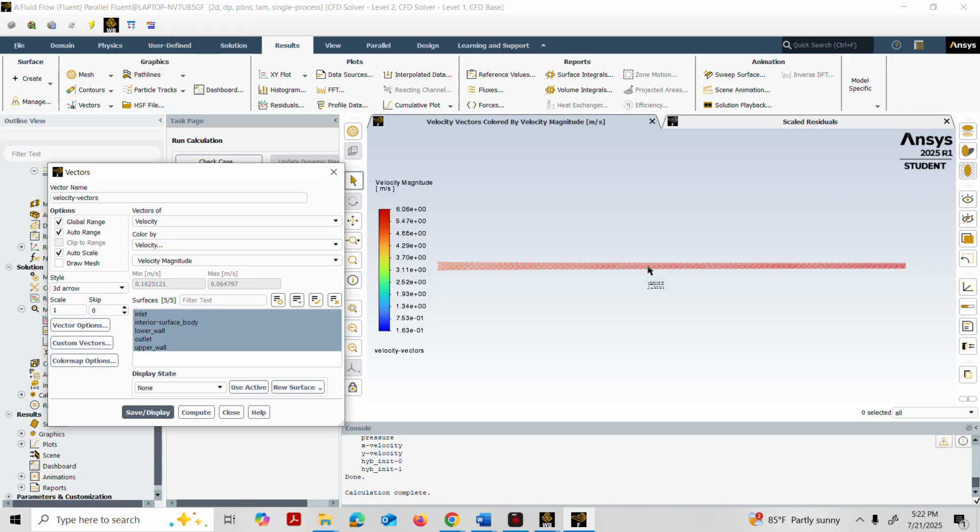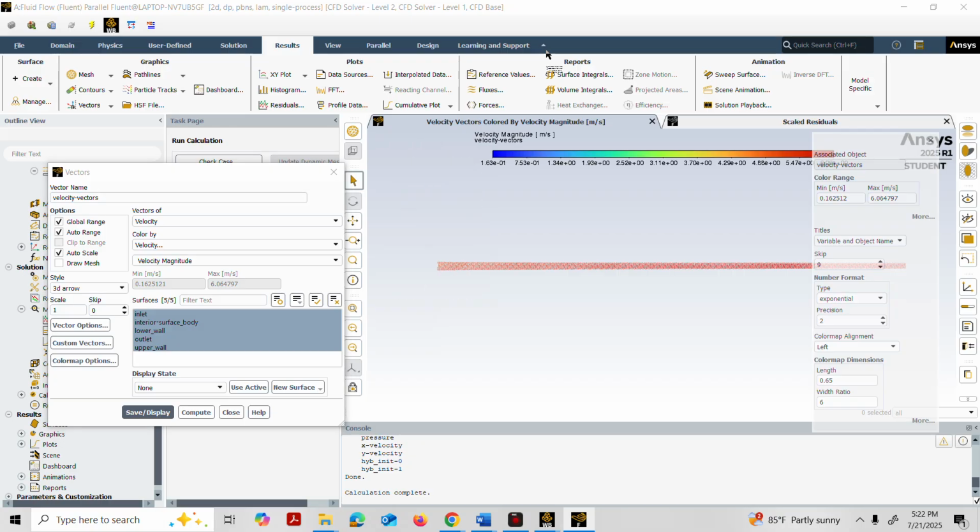So remember, this is hybrid Poiseuille-Couette flow. So we can move the legend out of the way and bring it to the top. Just click on it, hold it, and drag to the top. I don't like it. But it shows you the progression of velocity going from lower velocity, gets darker along the length. That means the velocity is increasing. Lower velocity at the inlet and increases to higher velocity at the outlet.